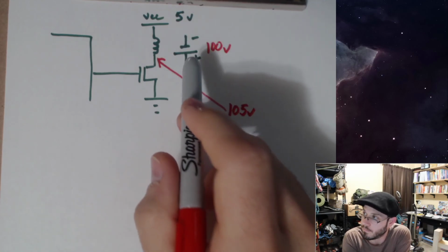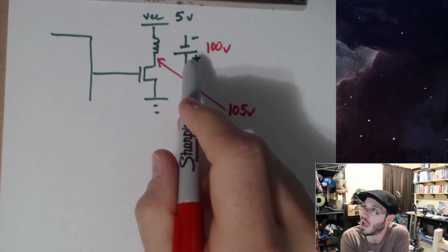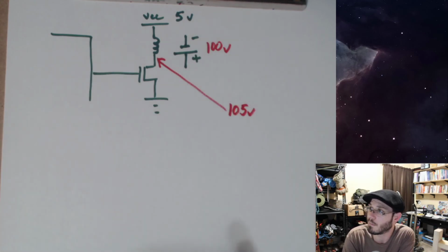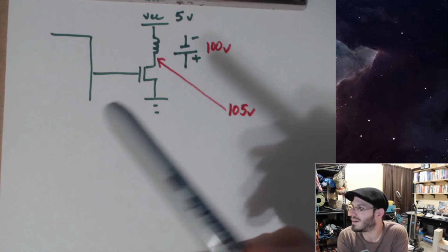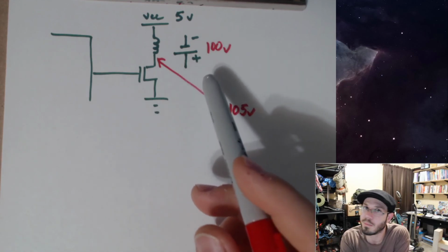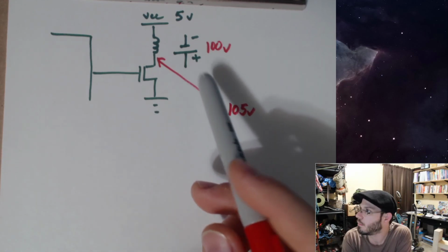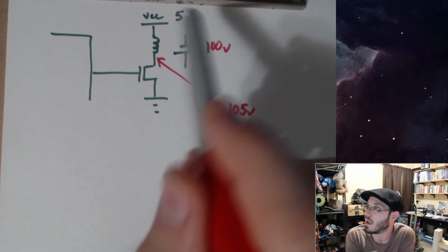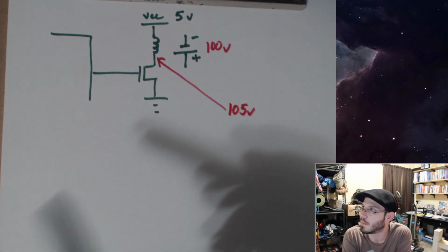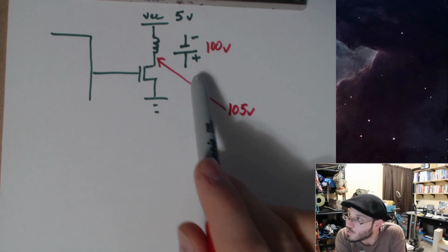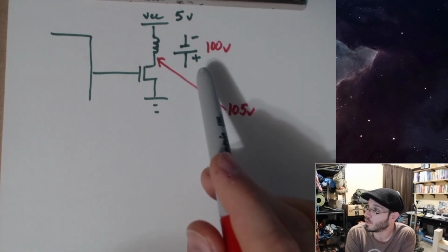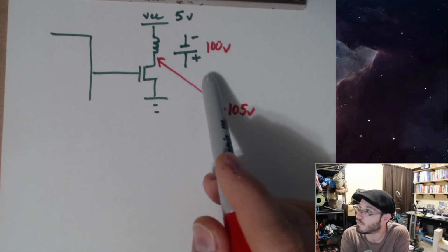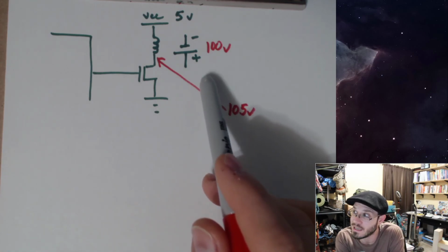So for this quick period of time, you get this voltage spike coming from this inductor. And if you want to, I could show it on an oscilloscope and hook up an example here if you wanted to see what this induced voltage spike looks like. It is quite large. It's actually quite frightening how large of a voltage spike you will get from a collapsing magnetic field from an inductor.